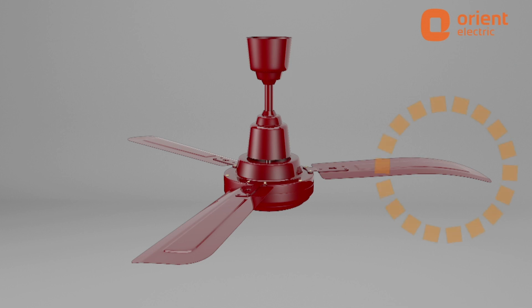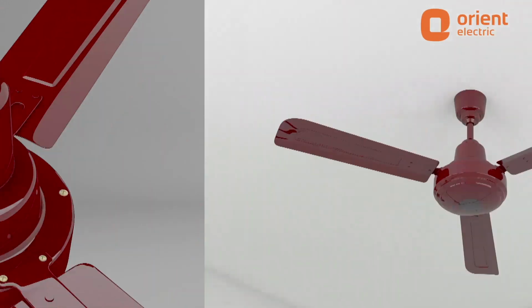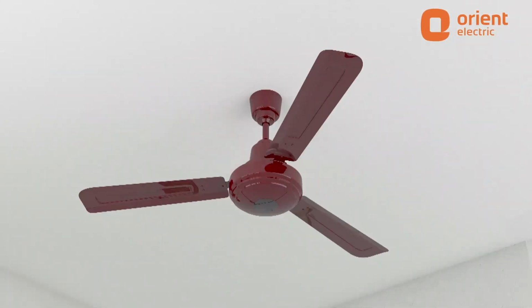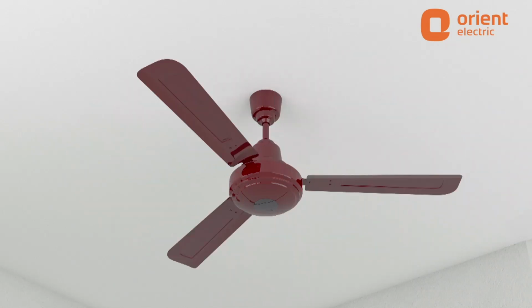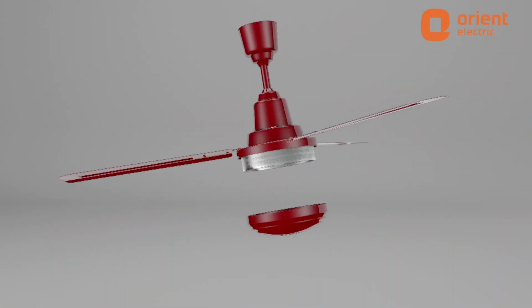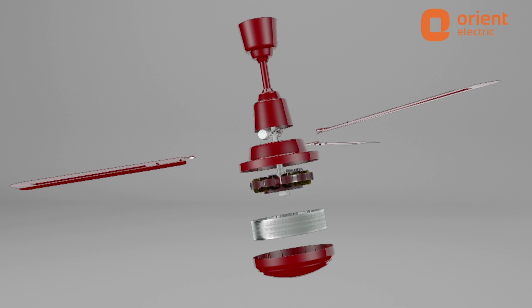In case the angle of blades are distorted or there is weight variation between blades, change the blade. In two-piece design, if the bottom cover of motor is unbalanced, you will have to dismantle the fan and then reassemble it after changing position.